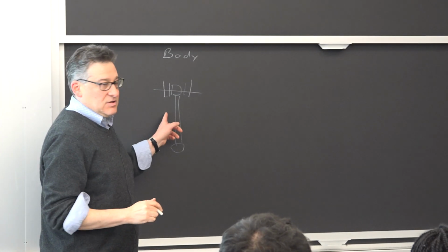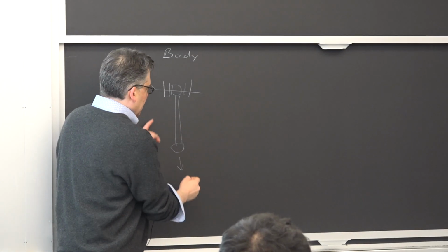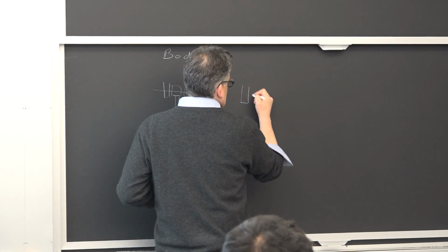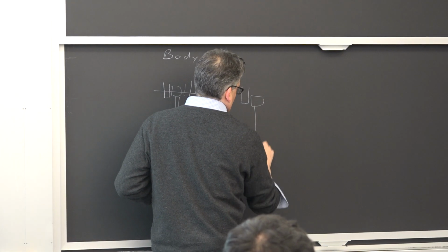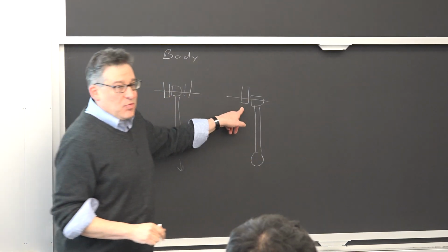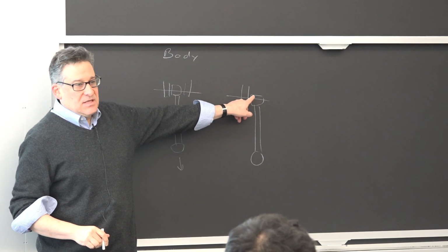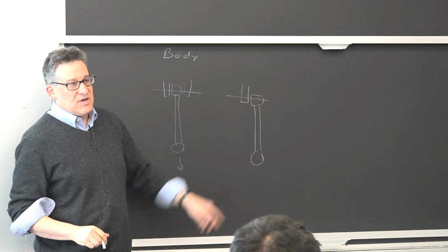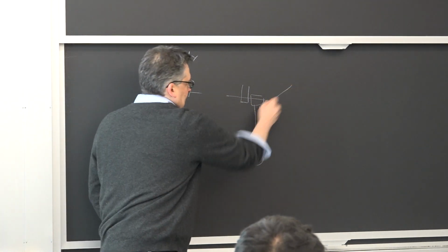This is double shear. This is the better way to do things. In some poor designs, you'll see there's only a single support, and then there's a bending load introduced here, which puts everything under higher stress. So this is the way not to do things.